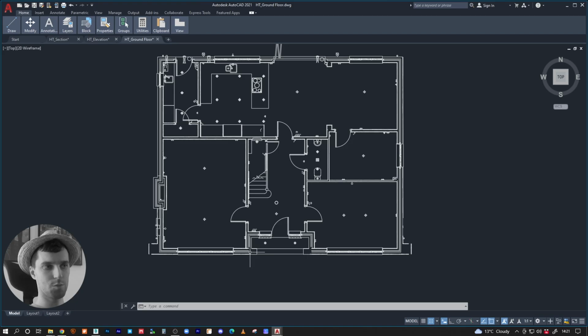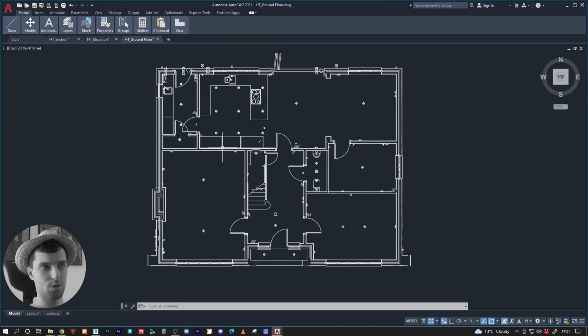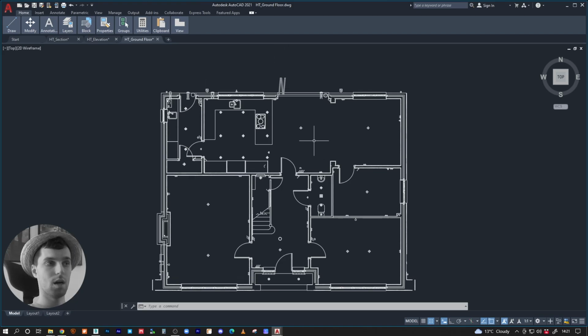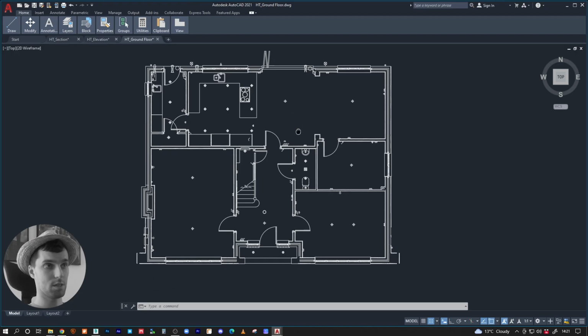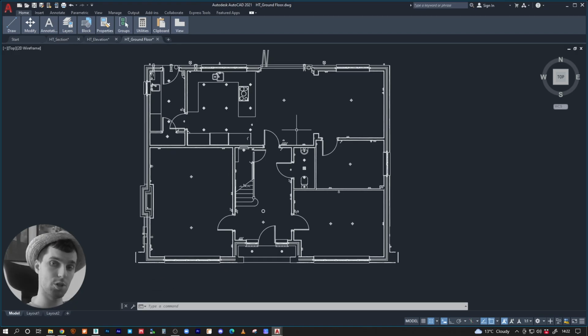Don't be afraid if a couple of colors are red or yellow. Doesn't matter. Maybe you didn't explode it to the end, and you still have a couple of different layers. But as long as you don't have a gajillion layers importing into 3ds Max, this is perfectly fine. Just have up to 5-10 layers. That's perfectly fine. Either way, inside of Max, you will be collapsing everything into one spline. That's very important, because the viewport is just going to work faster. If you just group it, that's not a good idea to practice.